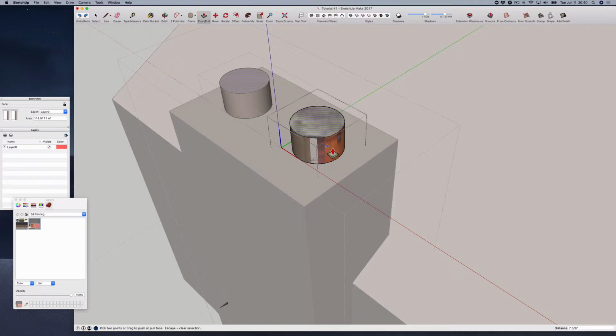So I've raised this up, and now you can start to see how texturing might be an issue on a round surface. See all the faces that this circle generated. I hit the paint bucket and I paint it, and you can see, oh my goodness, I need to reposition this. One big problem with round surfaces, notice there is no texture to reposition. You can make it a unique texture, but don't do that. We want to manipulate this and turn it into a color that would be similar to those clay pipes that you see coming out of chimneys. So what do we do?